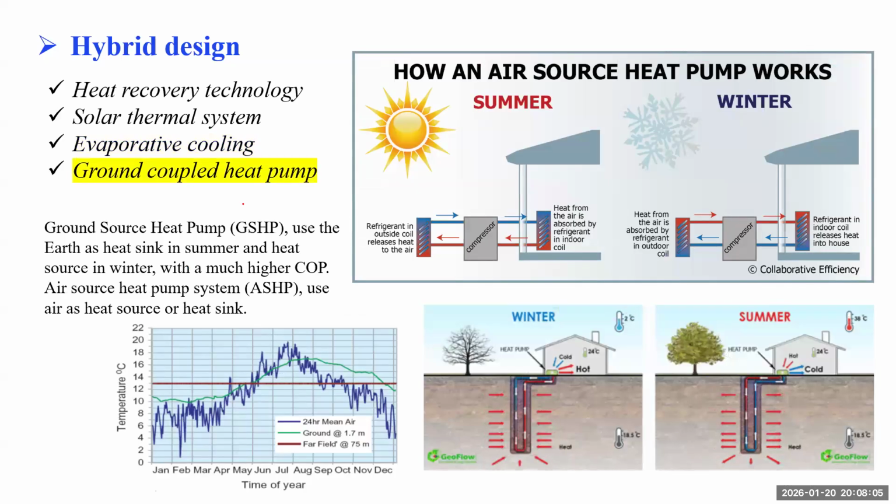And then the ground coupled heat pump. Last week, I think we understood the energy efficiency of our power plant and air conditioner. The efficiency is closely related to the ambient air temperature. For a heat pump or air conditioner, the outdoor air temperature varies with the seasons. However, the underground soil temperature is always constant. So we can reject heat to or absorb heat from the ground.